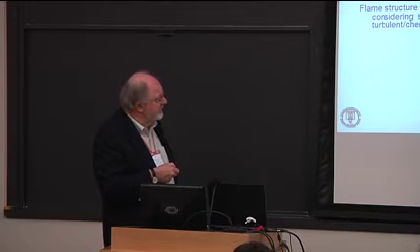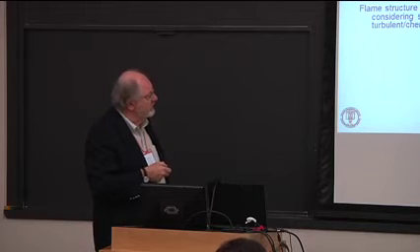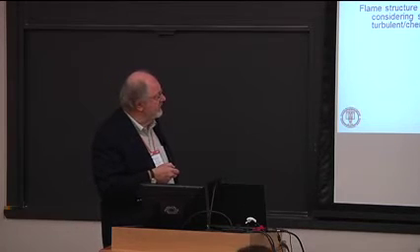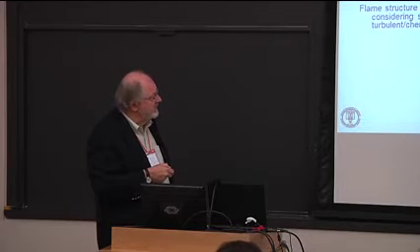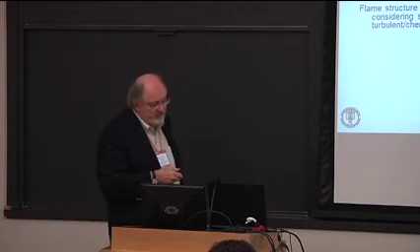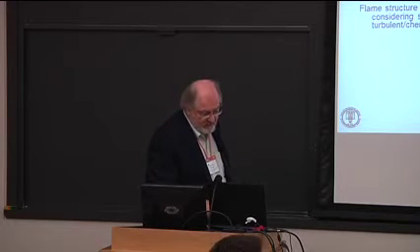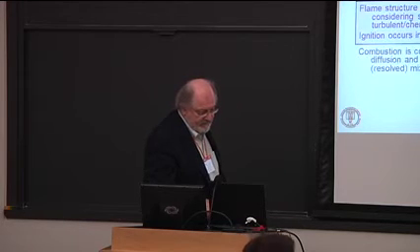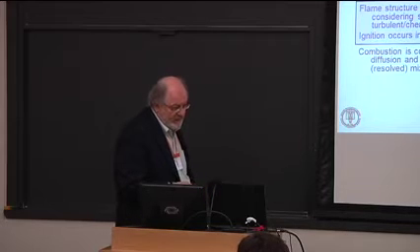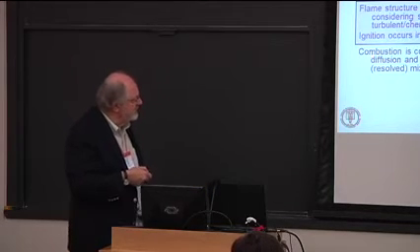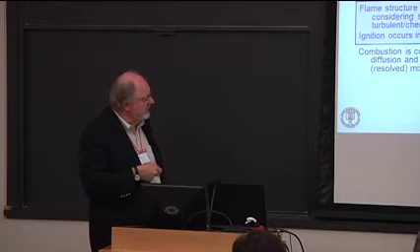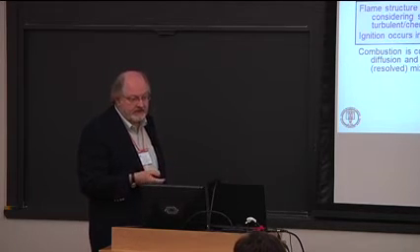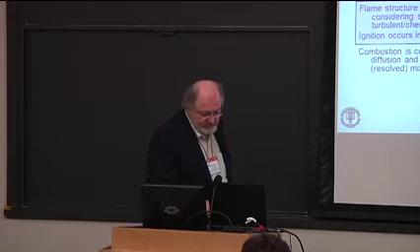have described, right? We have turbulence, which is entraining the air into this jet here. So turbulence is important from the standpoint of preparing the charge or mixing the air and the fuel. But the actual combustion itself occurs in this thin region where it's the chemistry that dominates. And we'll see that also a little bit more in a minute. Ignition occurs in regions where we have, obviously, premixed fuel and air. And as I just said, the combustion is controlled by large-scale mixing processes that are resolved in our RANS-type turbulence model.